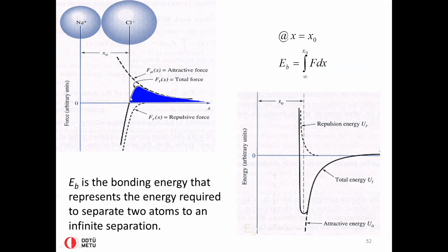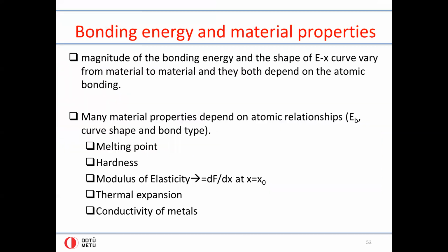Now, you might quickly see that the greater the slope, the more you will have to move along the force axis to be able to move one unit along the x-axis. So because of this, the slope here is related not only for this particular bond, but through a collection of bonds in a real material, it is related with the actual real-life difficulty with which the material will change its length along the applied force direction.